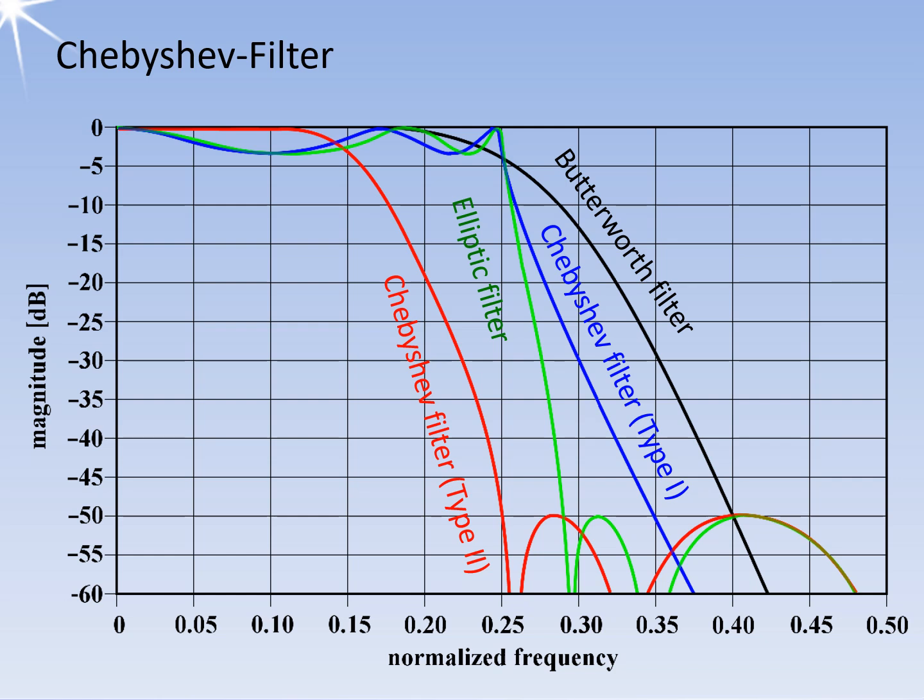The designs of IIR filters vary in the sharpness of the transition between the passband and the stopband, as well as in where they exhibit their different characteristics, whether in the passband or the stopband. The figure in the slide shows the magnitude responses of a typical low-pass filter designed using IIR filter design methods. Each filter has the same numerator and denominator order values. We have already seen the Butterworth filter, which consists of passive RC or LC combinations.